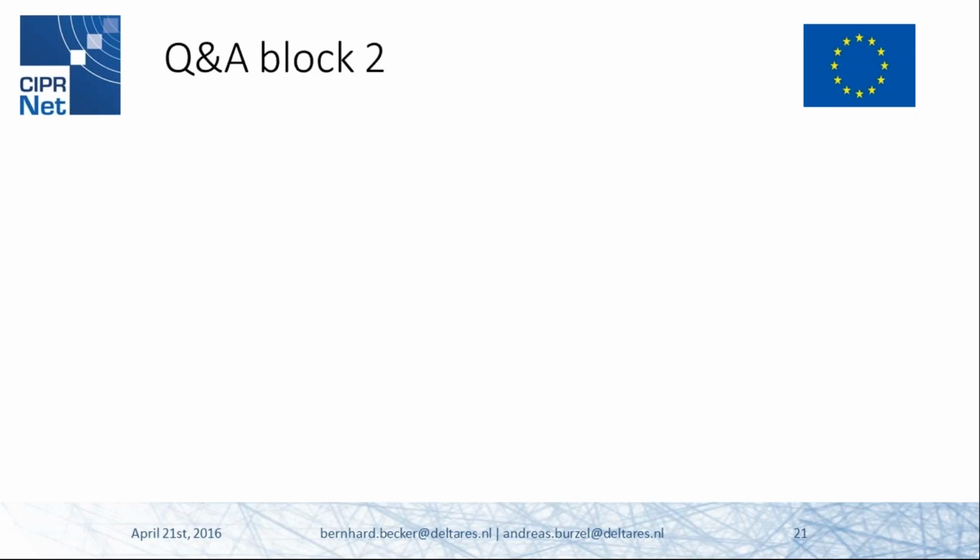Yeah, that's it. Okay. Can you say something about the computation times, Bernhard? Computing times usually in OpenMI 1.4 add up because we have a request and reply mechanism. So one model is computing, produces data, and then this data is taken by the second model, and the first model waits. So it adds up. And if you have iterative coupling, then it adds up again, but it depends on the number of iterations that are necessary. Okay, thank you.